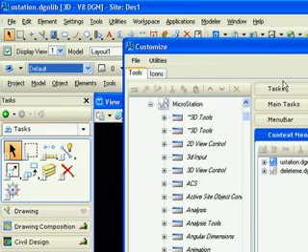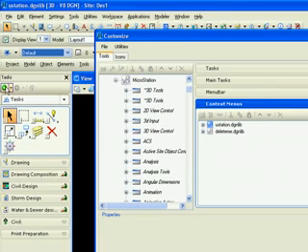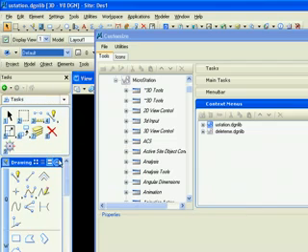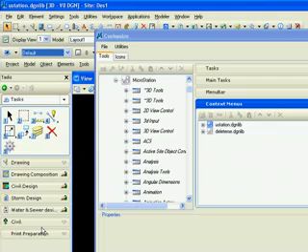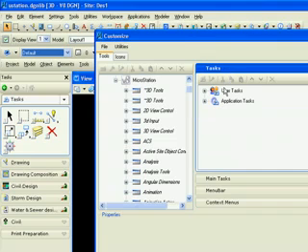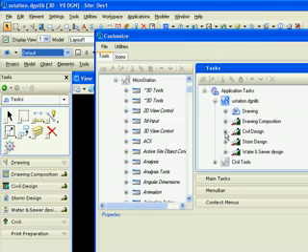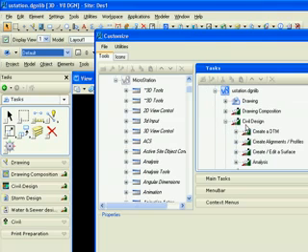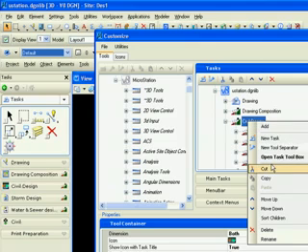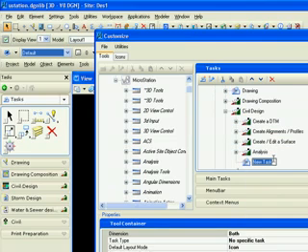Now let's look at how we construct a task. In this case, because I'm already home, my tools are grayed out. I may want to or opt to create another task that would involve building a pond. So I go into my main task application. I'll open up the library that's available to me, and I'm going to open up civil design, and I'm going to right click and create a new task. And this task will be called pond design.